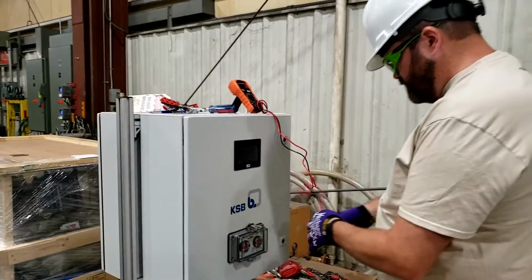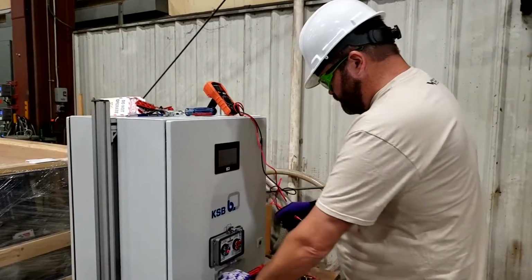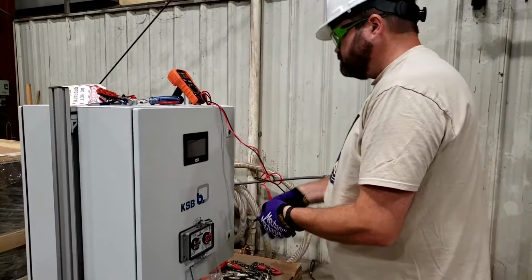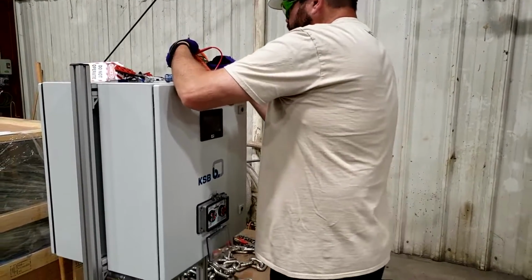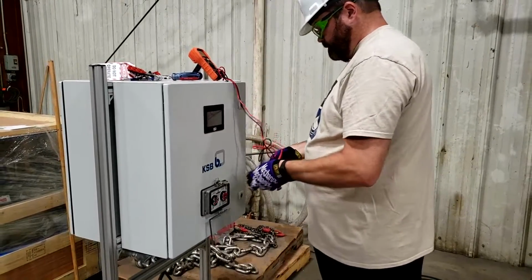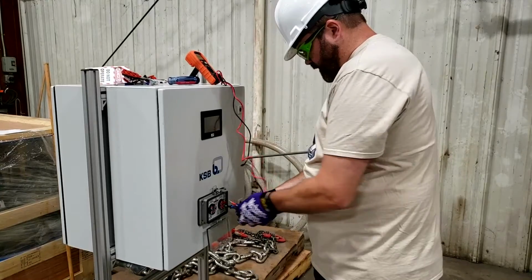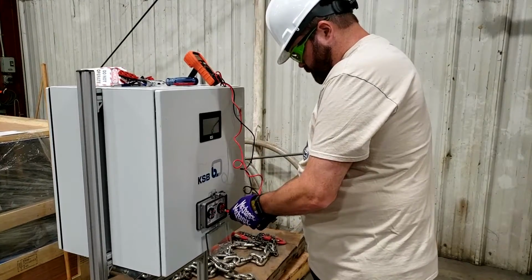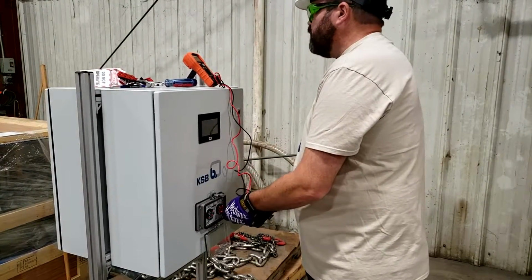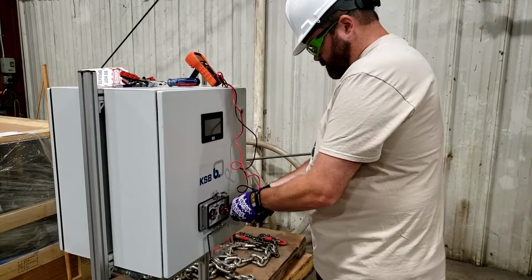Voltage present at the station. Open the door to the voltage test station, power on the multimeter. Turn it to the voltage setting. Using the multimeter, conduct the following 6 tests to verify proper voltage and to ensure that no equipment damage can occur prior to energizing the pumps.